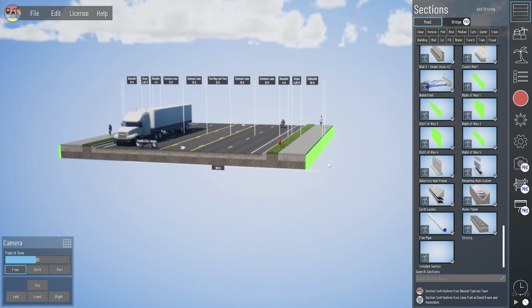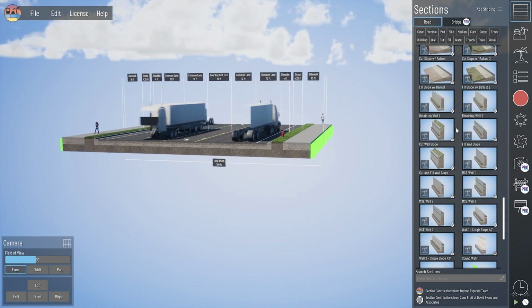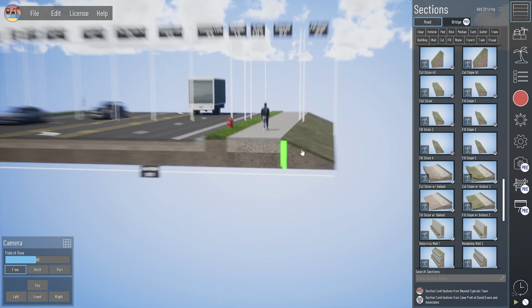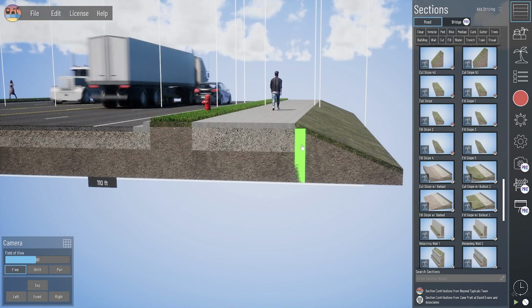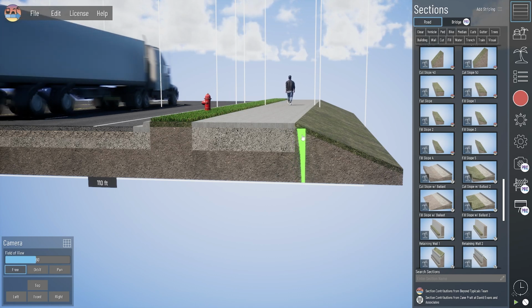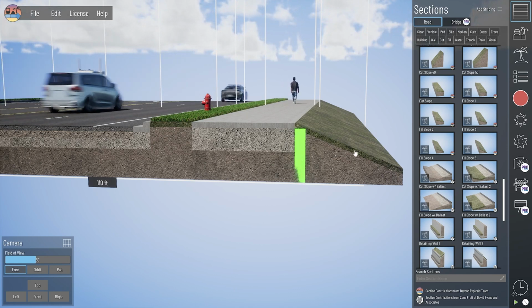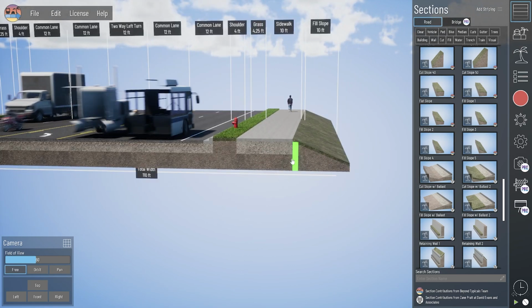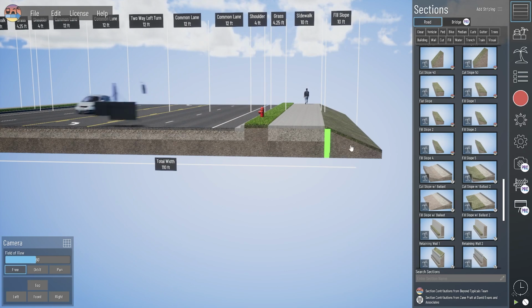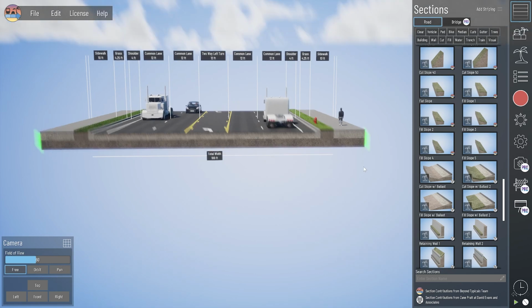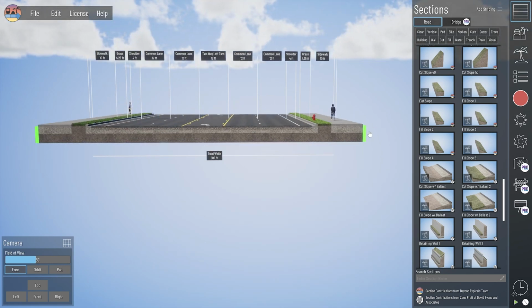Keep in mind that that negative width invisible section would start pulling other elements over the top of the adjacent section. So you'll see here I brought in a fill slope, and because our -1 width invisible section lies just to the right of that right-of-way section, it's pulling that fill slope over a foot to overlap. So there may be some use cases for that, but just keep that in mind here that we would probably want to just use that invisible section on the very end at a negative width so it's not bringing anything else over the top of those right-of-way lines.